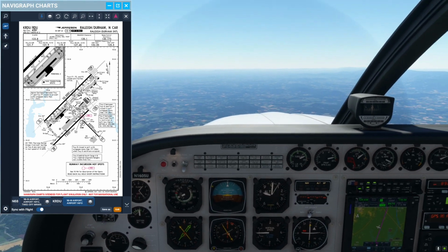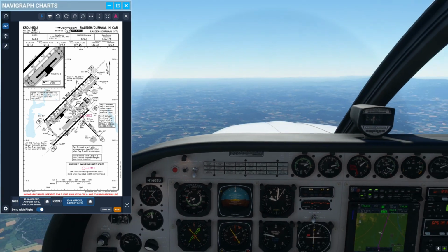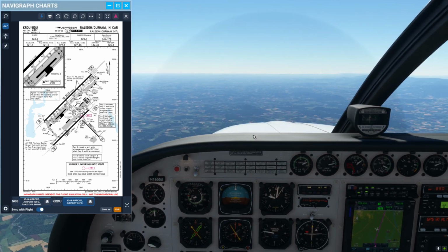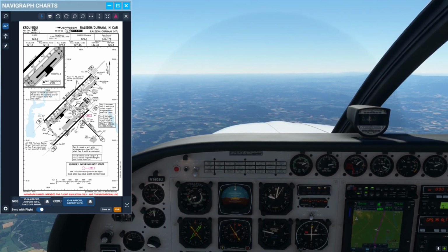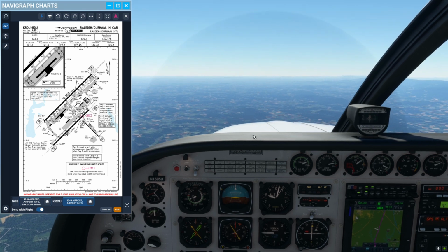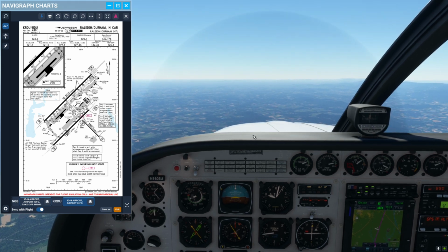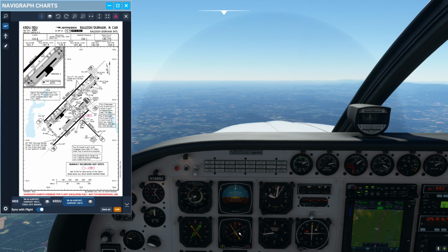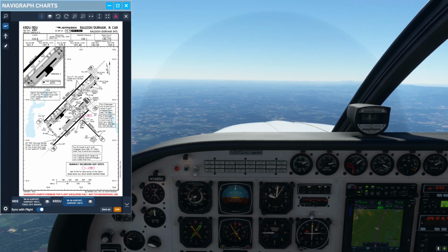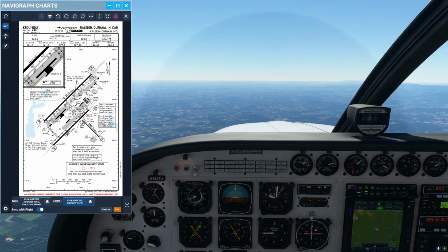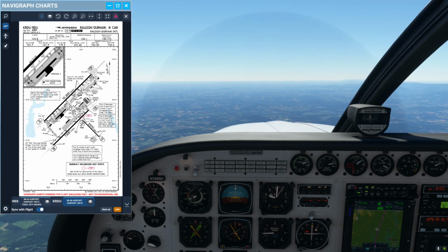I learned a long time ago to bug runway headings, and it always pays off, especially when you're flying a visual pattern. Well, everything's 90 degrees to 90 degrees to 90 degrees, right? So if you know where the runway heading is, when you set your downwind, this should be at the bottom, and you'll know you're flying the correct heading for the downwind. Especially when there's 0 knots of wind, you just fly exactly that.